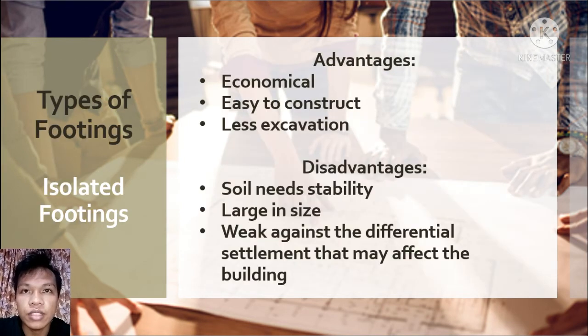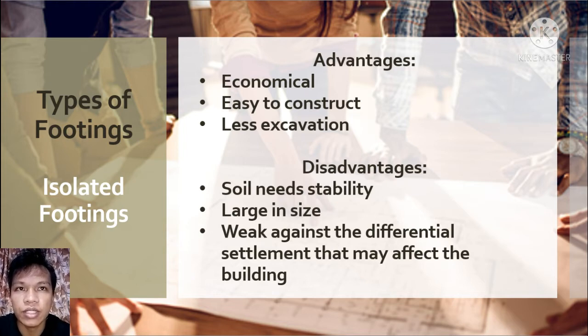There are some advantages of using isolated footings. First, isolated footings are economical. Second, isolated footings are easy to construct and require less earthwork. And there are also disadvantages, like the soil needs stability all around the base of the structure. The footing to cope with a high load can be very large in size. Separate foundations make this design weak against the differential settlement that may affect the building.